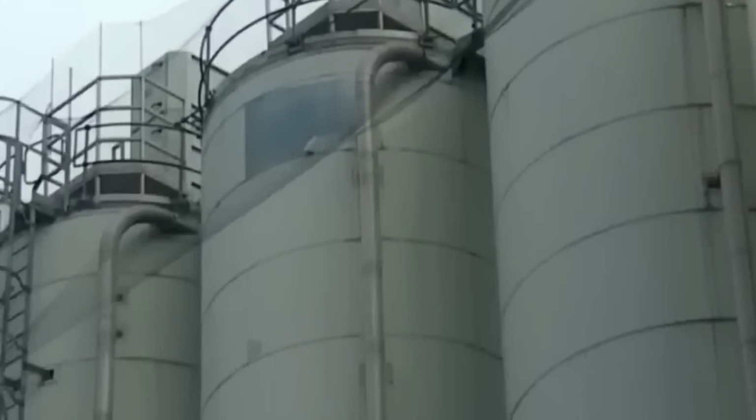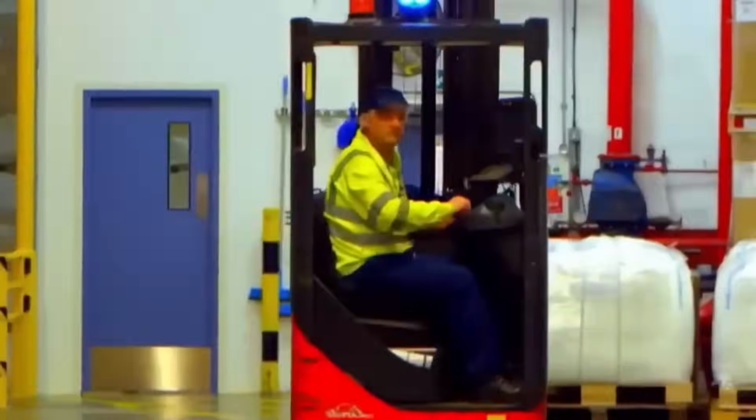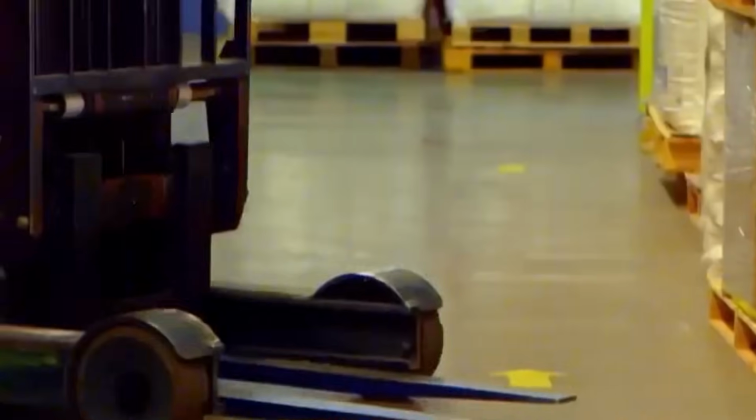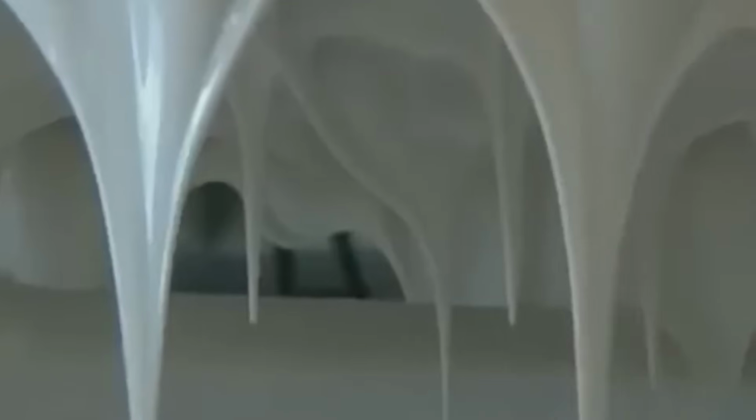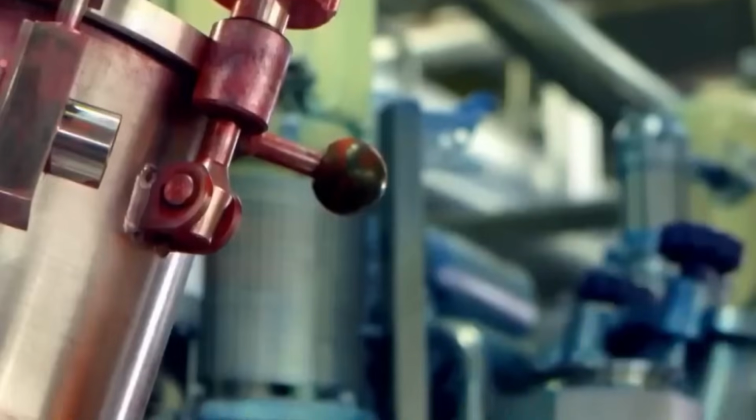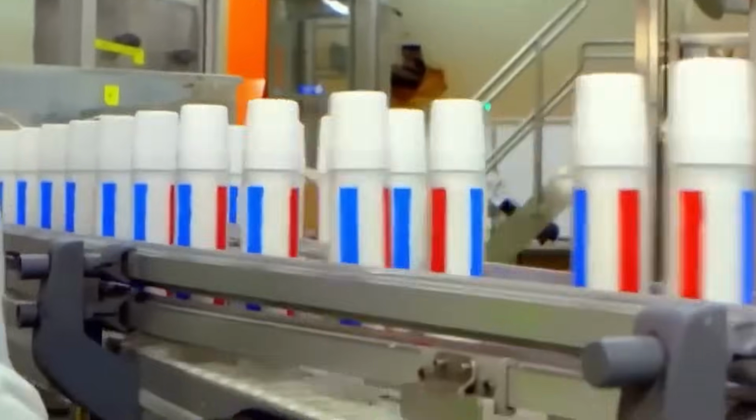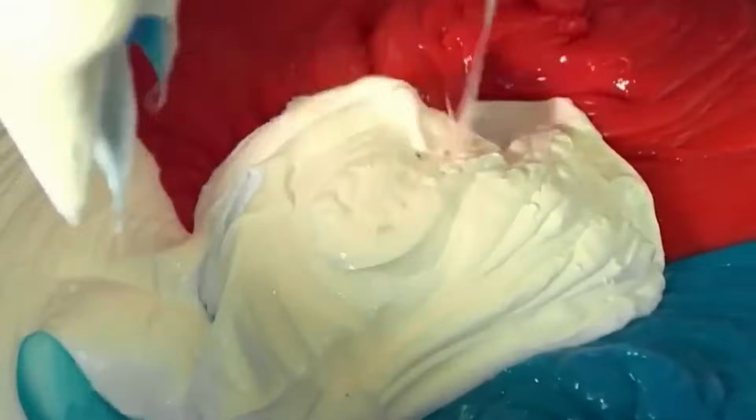Final packaging lines are equipped with vision systems to detect carton defects, misalignment, or barcode errors. These systems use high-resolution cameras and rejection logic to divert non-conforming packages. High-speed toothpaste production lines are capable of producing over 300 tubes per minute, with batch sizes ranging from 1,000 to 6,000 liters depending on demand. Formulation changes are executed by software-driven recipe management with automated valve sequencing and ingredient routing.